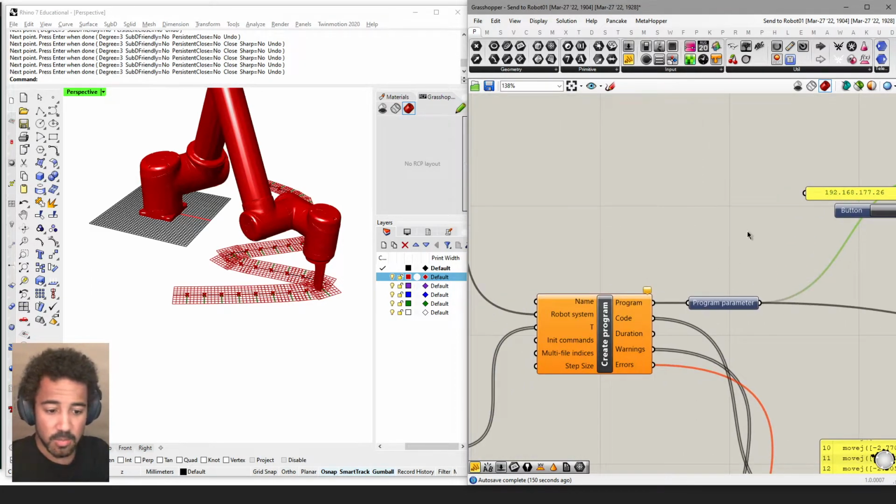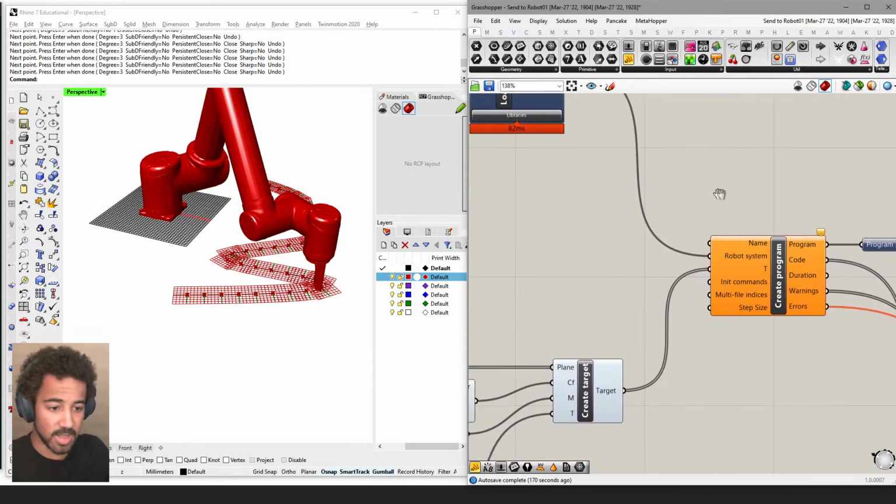It is very convenient to, instead of the robot just starting to move immediately, have a pop-up on the robot pendant that allows us to actually move from our laptop to the robot, get the pendant in hand, be close to the emergency button, and then we can press play and actually have the robot move then.